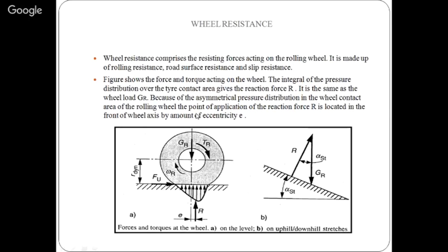This resistance force comes into action a little shifted from the center by E. Clear? When it is shifted from the center by E, then the vehicle will need more power and torque to accelerate in that condition. That's why the specifications are there. Maintain your tire pressures.